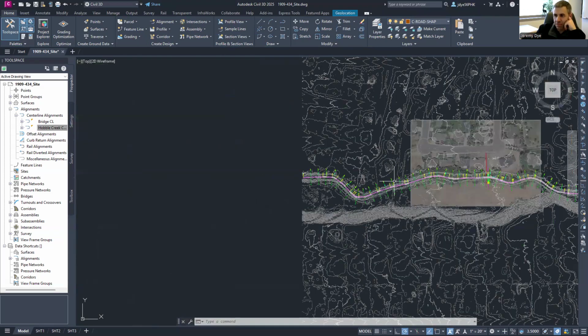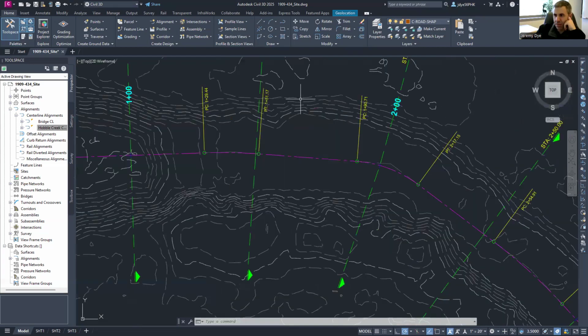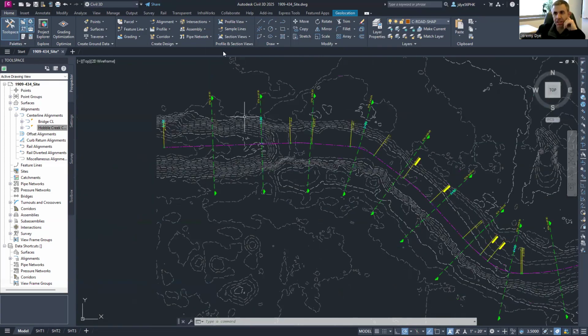So I'm going to come in and basically I'm going to be tracing the bottom of this contour line, change in slope. So I have steep stuff here, flat stuff here, and I'm just going to trace roughly. And the only place it matters is where the sample line crosses the bank. Everything in between the sample lines is data that's lost, so don't bother modeling it. It's a waste of time.